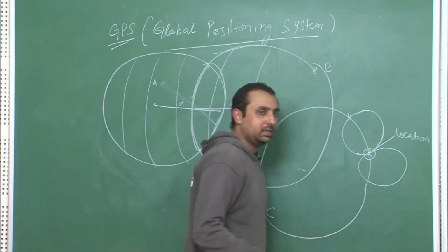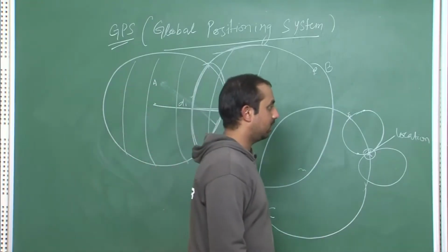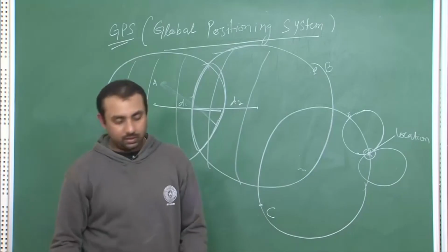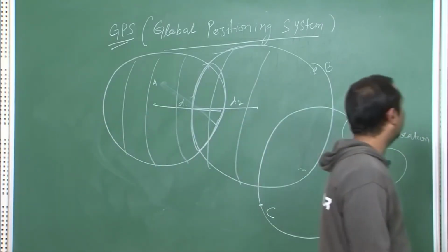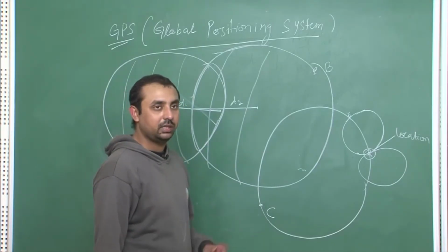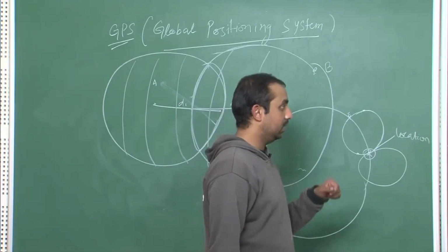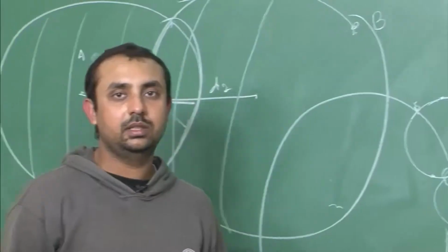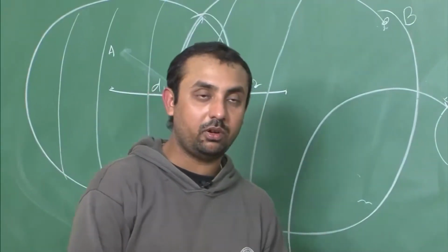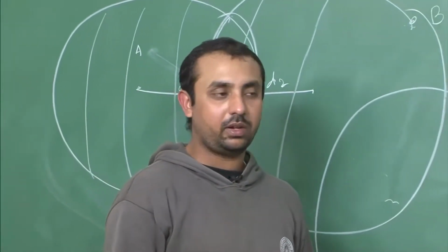As far as the sensor part is concerned, these were the major sensors which I wanted to discuss, to give you an idea of how these sensors work, what the general principles are, and how data are acquired using these sensors. We will demonstrate this with small examples. We will also share the code for the accelerometer and rate gyros, as well as for the angle of attack sensor, and show how to acquire data using an Arduino board, MPU 6050 sensors and the angle of attack sensor.